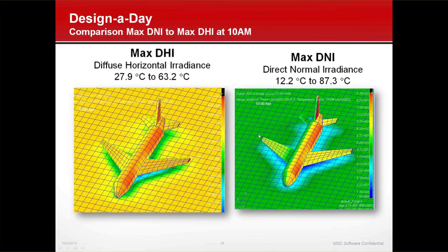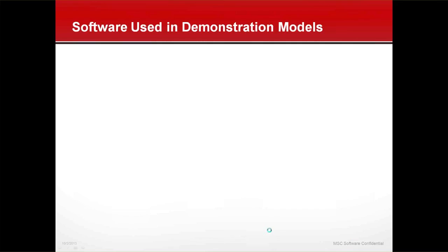and at every hour during that 3-month span, create an artificial day that will encompass the worst we could ever see. And here's an example of an airplane sitting on the ground where we did a design day where we had what we call the max normal, the moving sun was max here, and here this was the max diffuse, and so it actually didn't get as hot. The range was much less, and you can see the shadow on the ground, this concrete runway, because it's being shaded, and there's interaction, radiation, and you can have convection interaction with the ground if you want to add that. So if you do have a spacecraft on a launcher or sitting out in the sun or some environmental loads, we can do that.